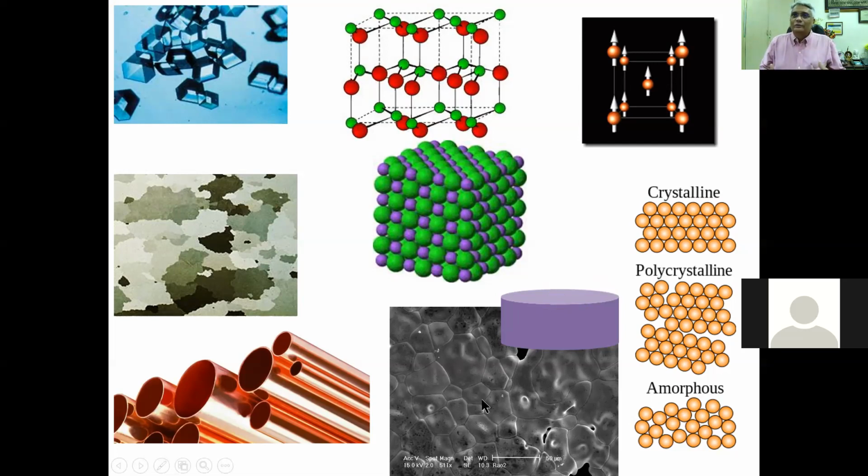So, well, you can go to higher temperature of sintering, that way the grain boundary widths can be reduced. But then as you increase the temperature, there may be a loss of certain elements from the polycrystalline bulk or matrix. That could be one of the issues. See, that also is shown here. The complete missing material, leaving a big void there. This is completely unwanted. But a polycrystalline system has all these associated problems.